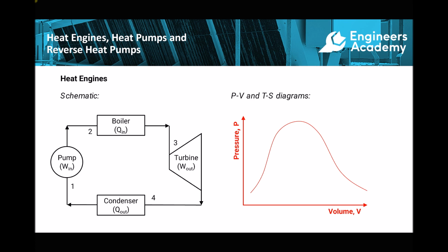Now, if you've watched our earlier tutorials, then you'll already be familiar with this type of diagram. But essentially what we have on the left hand side of this curve is water. Underneath the curve, we have a mixture of water and steam. Essentially what we have under here is wet steam, where we have a combination of water and steam as it's converting from water into pure or superheated steam. If at any point we're sitting directly on this curve here, we would have dry saturated steam, so we're at the point where all of the moisture has been removed. And over on the left hand side here, we have what we call wet saturated steam. So we're on that point where we're converting from water into steam.